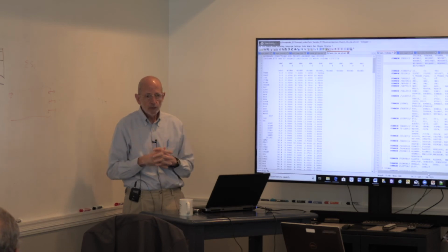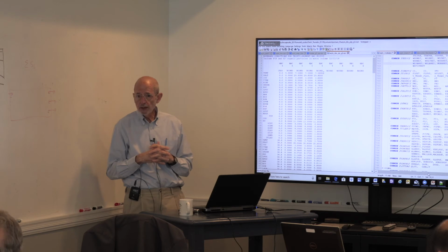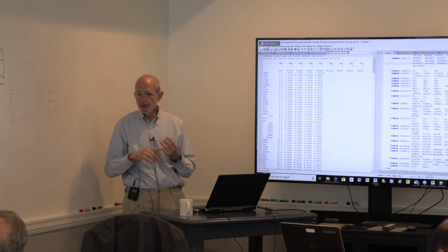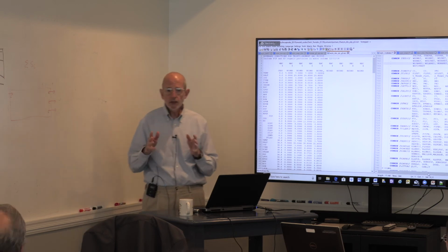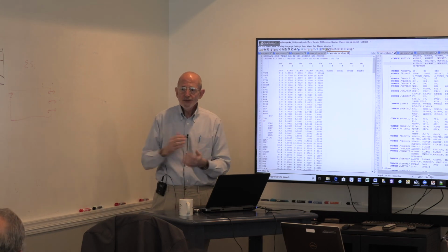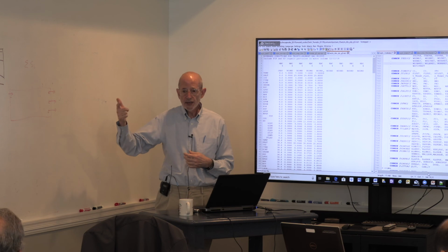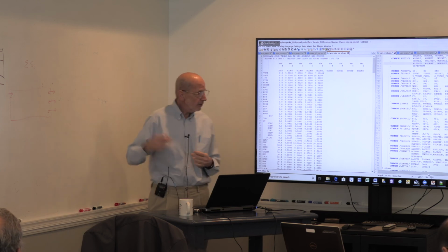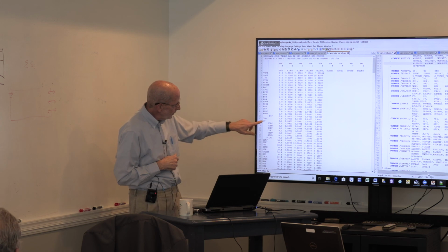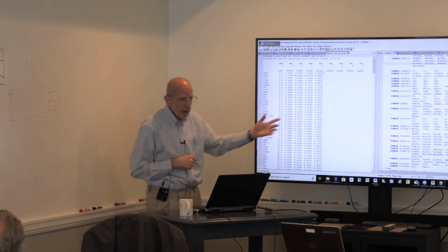It's just convention. Loads that come from the watershed model, we treat as loads, and therefore we give them 0 for the boundary condition. So for the carbon, the nitrogen, the phosphorus, the boundary conditions at the inflows are 0 because we load it. For things that we don't think of as masses, things that don't come from the watershed model, like temperature and dissolved oxygen, we give them actual boundary conditions. So for example, here's dissolved oxygen. It's 8 in the Susquehanna River. It's 11 at the ocean interface.